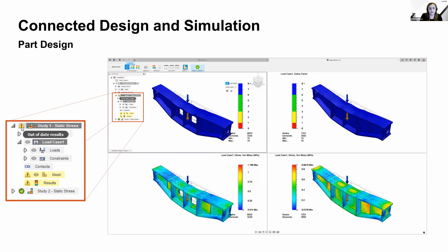This lets the user both simplify the CAD model to remove features that don't impact simulation, in turn minimizing the solver time, and it also provides a place to draft up different design changes. Any changes made to the geometry using this function do not reflect in the actual CAD model, so it's untouched within your design workspace, making it that draft state that I mentioned.